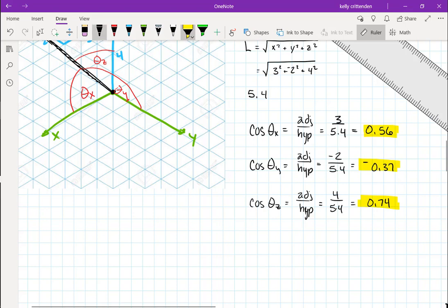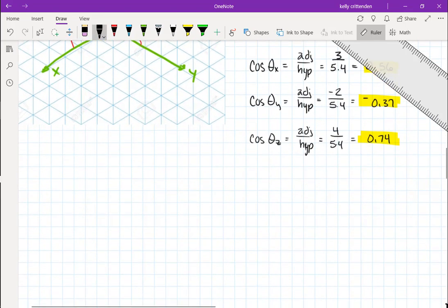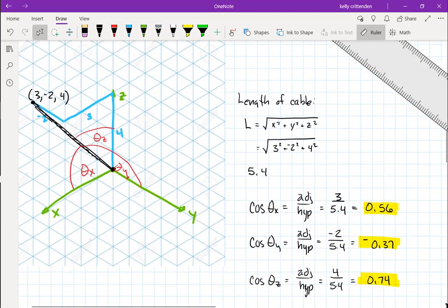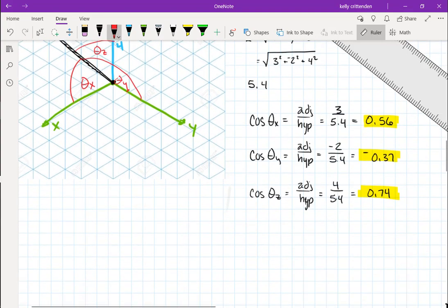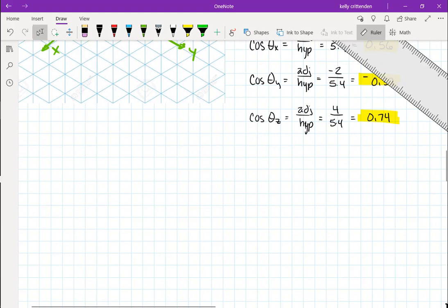For instance, you could imagine that I want to solve for a... this is not a 3D concurrent force system. I only got one cable on it. I don't even show a force. We assume that there's a force over here somewhere. But let's make that force and call it F. Part of solving that, assuming I did have the other two cables and whatever external forces applied, then I would want to solve the equations: summation of forces in the x direction equals 0, in the y direction, and in the z direction.